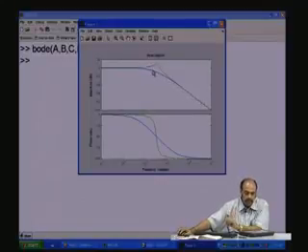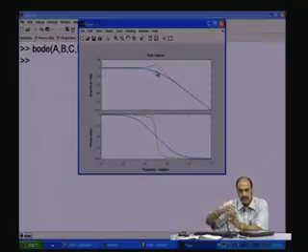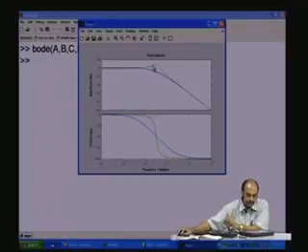No problems, because the two poles were quite close to the real axis. Once the poles start shifting away from the real axis, it is going to peak. There is a resonant action here, and that is peaking, which is giving an amplification of the gain, and then it goes down. And you see the difference also in the filtering action. This is a much better filter compared to the earlier one.